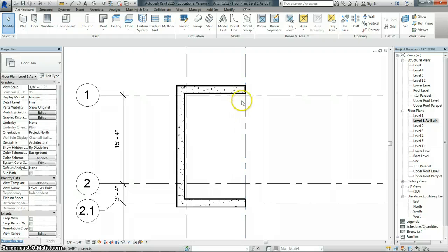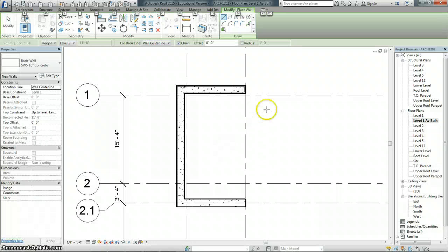So what they've done is it'll be 8 inches on this side and 4 inches on this side so that it lines up, because as we start to look through here, and we'll add this later, there's a precast floor that'll come over and sit on that 4-inch shelf that's coming along here. So we need to make sure we build this correctly, so when we draw that later, that will all be correct. So I'm going to come up here and get us ready.